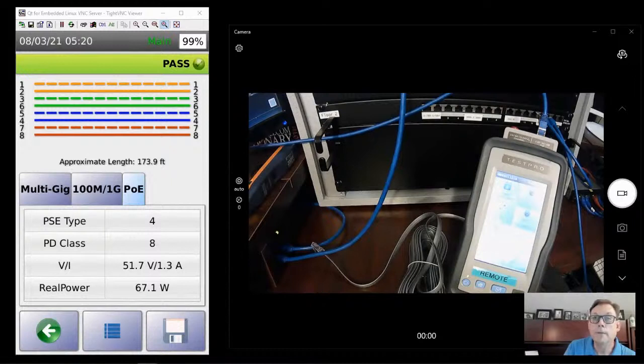So if you have a network that's functioning perfectly and you run an SNR test on it and everything on there is showing up at 6 or 7 dB, then that needs to be your benchmark, because maybe you want that to be your bottom line. But 3 dB, once it starts getting below that, the closer you get to 0, the more issues you're likely to have. There was also a question related to DCR.